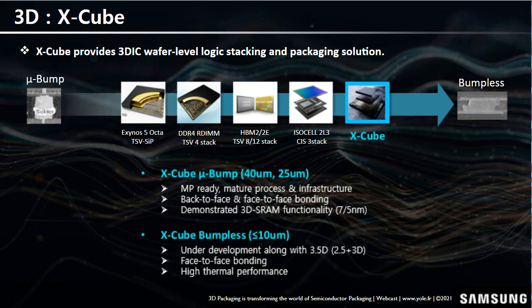So 40 means it's more like a die-to-face bonding through TSV. That's why we're having a 40 micron pitch. And in the face-to-face bonding case, there's no TSV for the logic-to-logic connection. That's why you can enjoy 25 micrometer pitch.